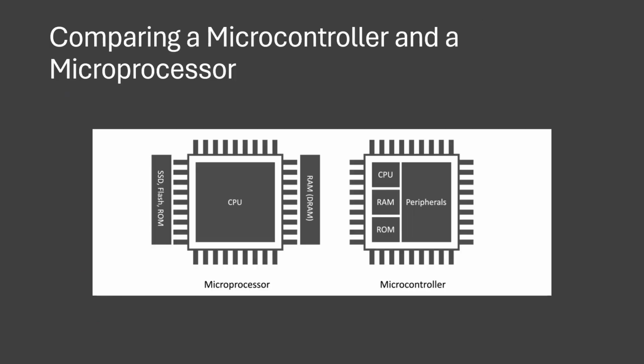Now, before we look at the comparison of microcontroller and microprocessor, there are different common architectures of microcontrollers out there. We have the AVR type, which are popular in hobby projects. These are the type of microcontroller we have in Arduino, in the Uno and some AVR chips. We also have PIC. PICs are basically used in industries, and they are known for low power consumption. And lastly, we have ARM. ARM is very common, powerful and versatile, and is found in our smartphones and in more complex devices.